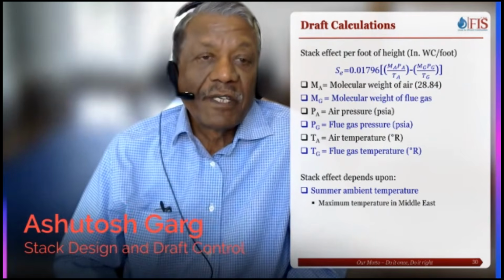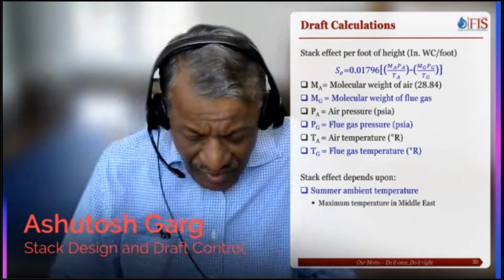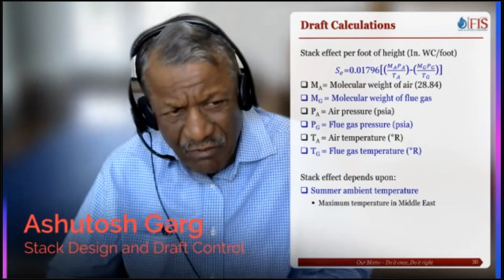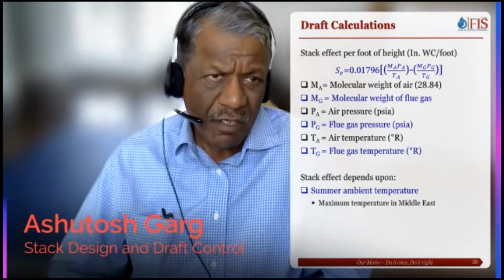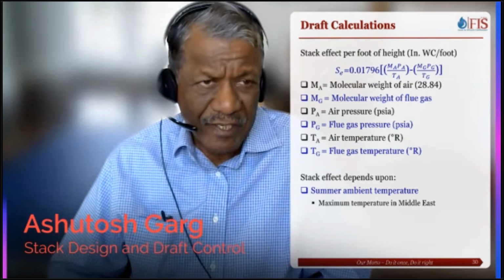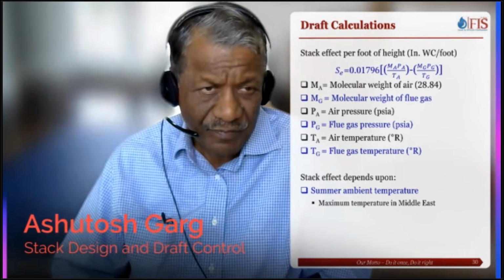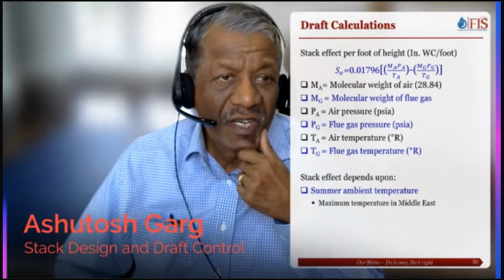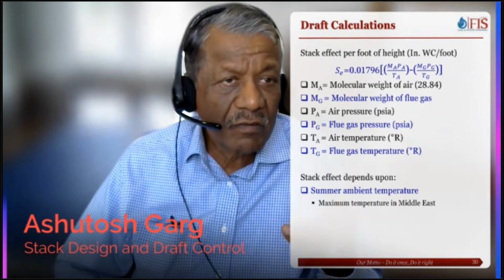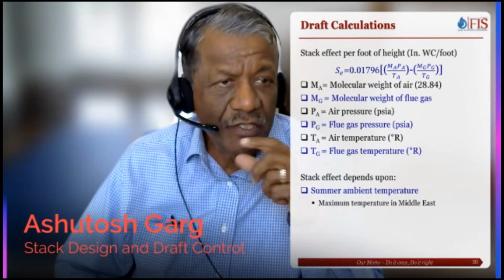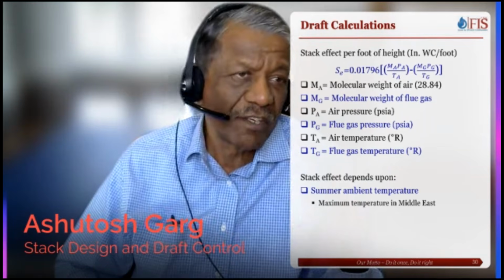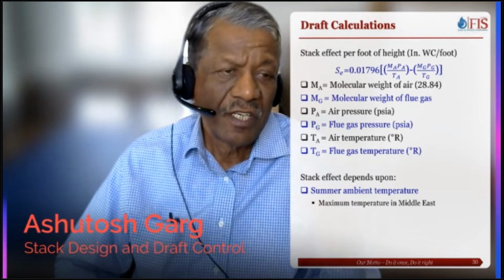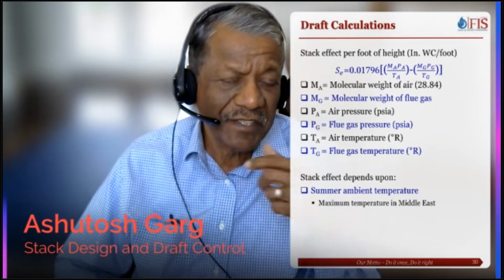Let's turn to a little bit of calculations. I don't want to scare you with the calculations, but these are very simple, and you can calculate the stack effect using a very simple formula. Given over here are the molecular weight of air and molecular weight of flue gas, almost identical, air pressure, flue gas pressure, air temperature in degrees Rankine, and flue gas temperature in degrees Rankine.